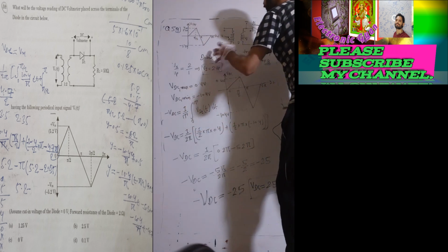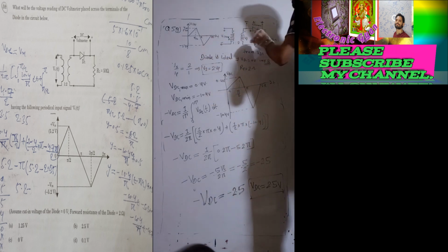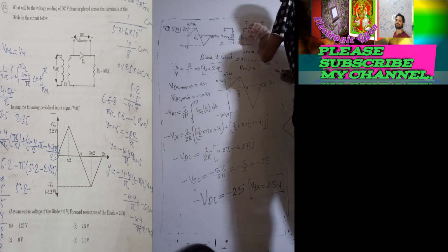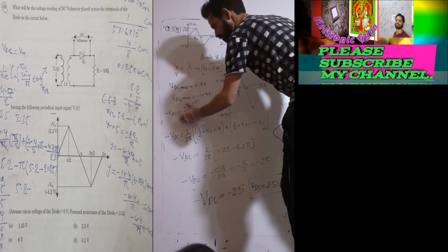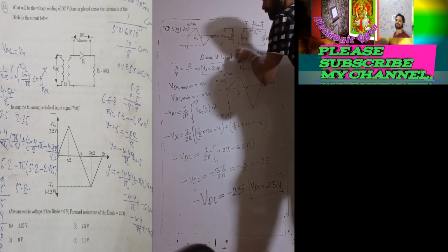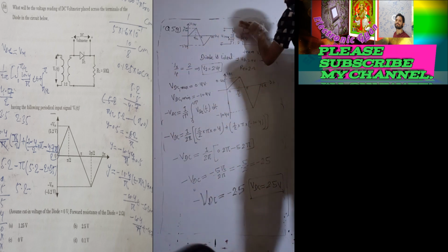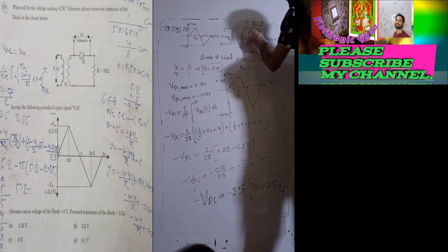We just have to calculate the average voltage. The average voltage across this diode means the DC voltmeter reading. That is what we have calculated here. This is the DC average voltage across the diode, which is the DC voltmeter reading, and its polarity is just opposite of that of the diode.